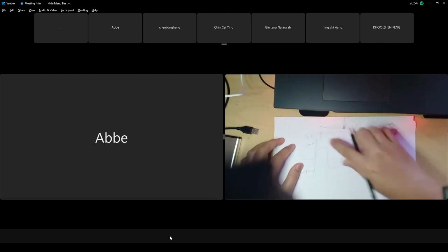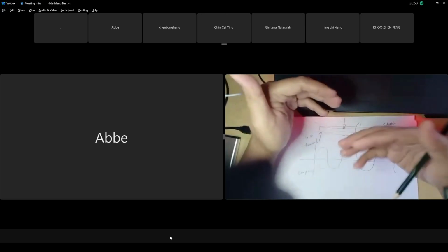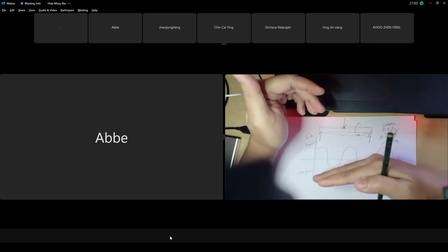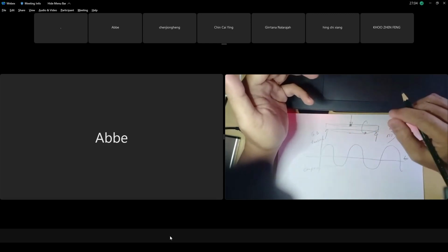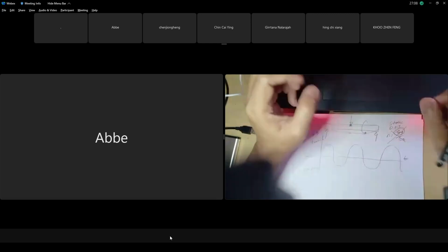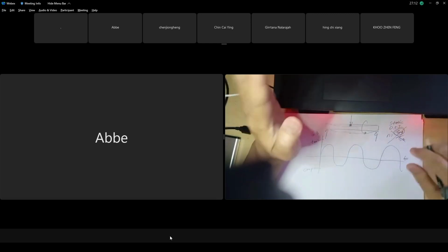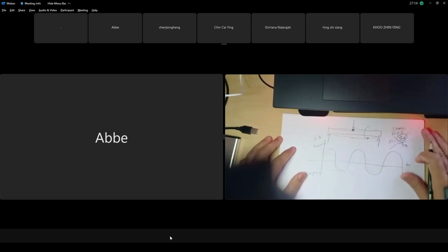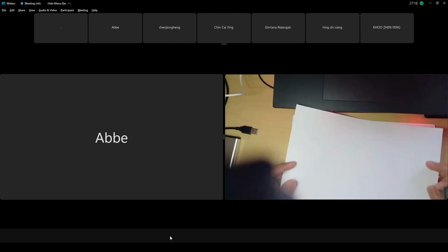Because this shaft sustains a bending load, we calculate stress. The load is fluctuating from positive to negative. This is an example of fatigue loading. So this will weaken the shaft material. We can no longer use SY. Remember why fatigue loading is critical. We must study fatigue, for example with a rotating shaft.